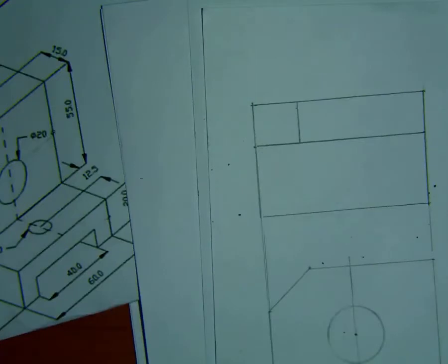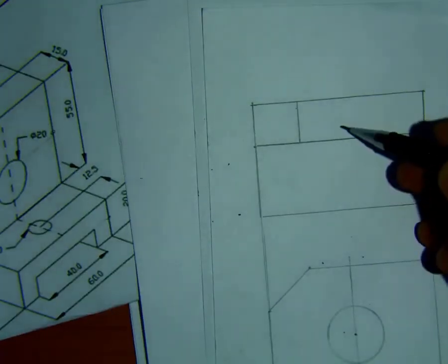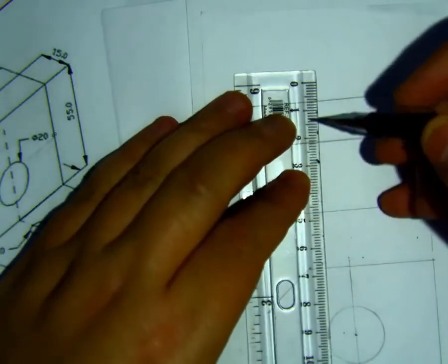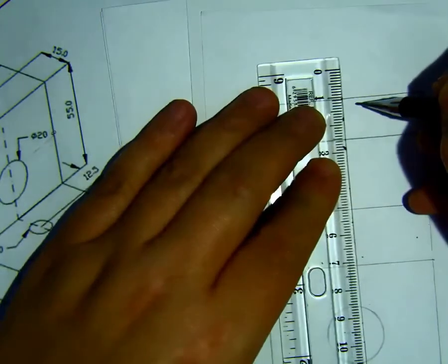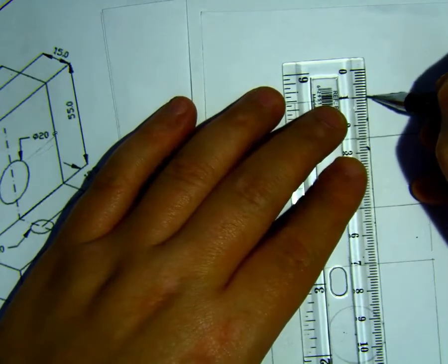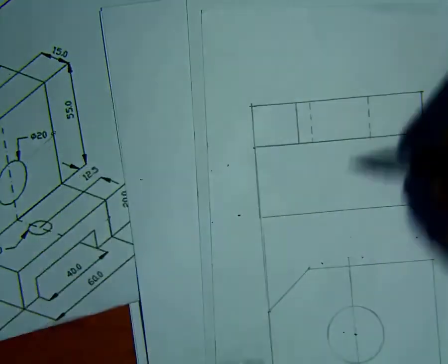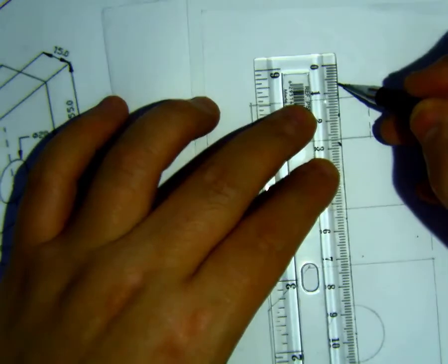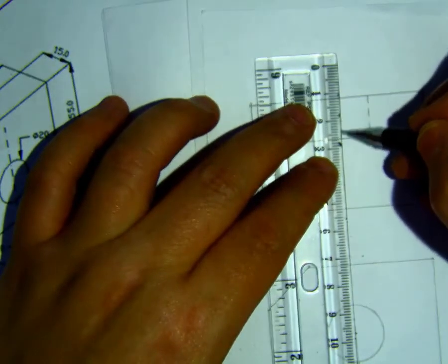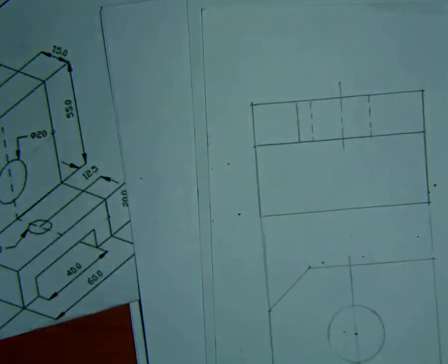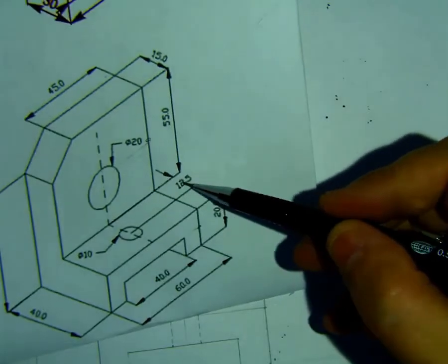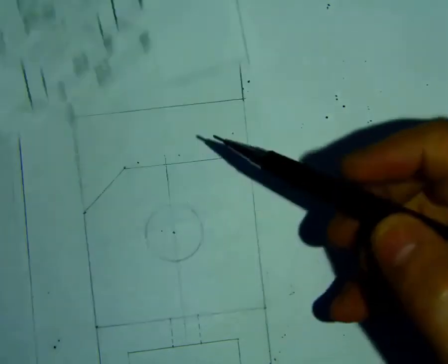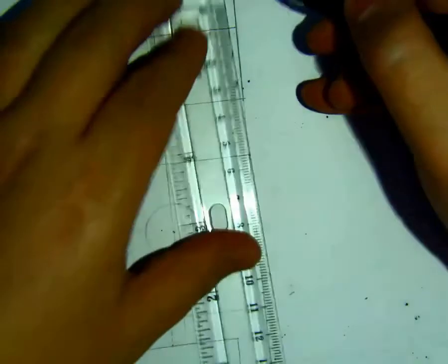Okay, so here is my drawing. I can add a hidden line for the circle here, like this in the top view, if you want to be precise, and a center line, of course. Also for this circle in the top, they are giving you a dimension. They are saying it's 12.5 from this edge. So I will go from this edge 12.5.